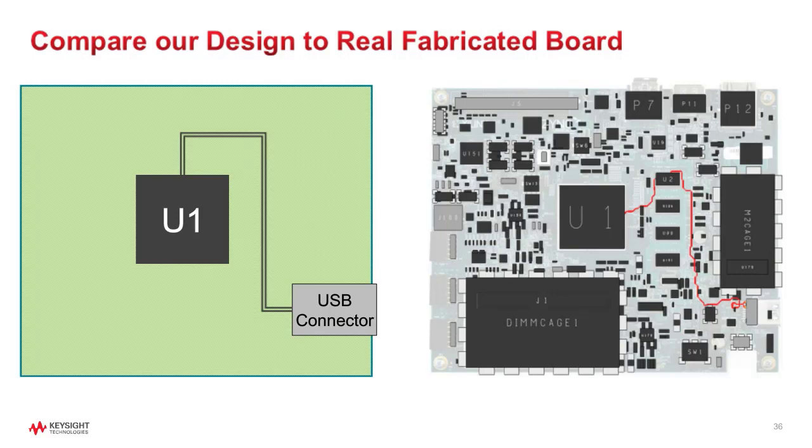Everything's included within the same ADS environment, but SI Pro stands for Signal Integrity Professional. It helps you quickly take your board file, be it BRD, Gerber file, or ODB++. We can take that in, import it, and take a look at a 3D view of your board and extract the 3D EM simulation and use that result in the channel simulation. So we'll take a look at another demo video with SI Pro, and we will come back to look at what we expect from the traces.